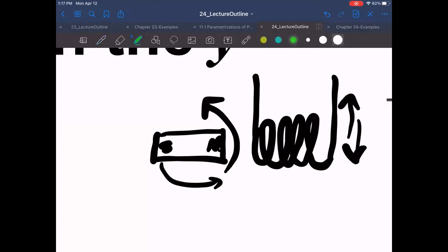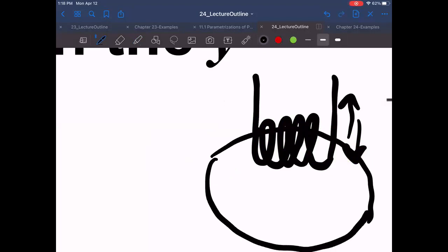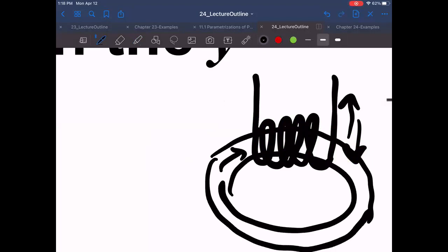Maybe I could do something fancy where, say, instead I made a ring magnet. Maybe I made a circular magnet, right? With all the magnets pointed in one direction. I don't know, I just had this idea. But then as it would spin through there, there'd be no change in flux and I wouldn't get any current. So this would produce no current for me. It has to increase and decrease. You have to change it.